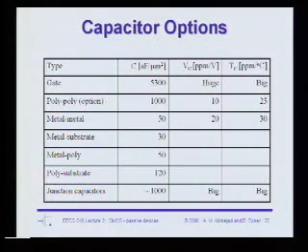So here is, in a typical CMOS process, what we have available to us, right? Anything you put on top of the substrate is a capacitor. The question is, is it a good one or is it a bad one? Well, good in this sense would be density. The more dense the capacitor is, the better, because that way I can make it smaller. Doesn't cost me as much, but also the smaller I can make my capacitor, the less substrate parasitics it'll have. The substrate parasitics, sometimes called the backplate parasitics, are an issue.